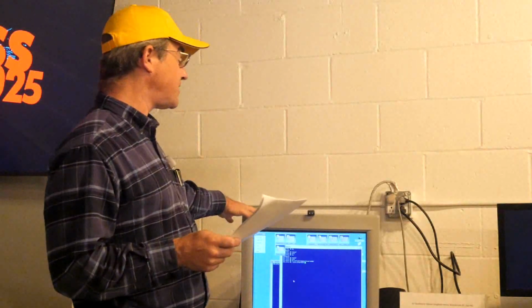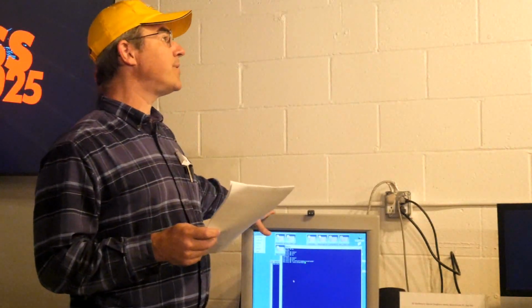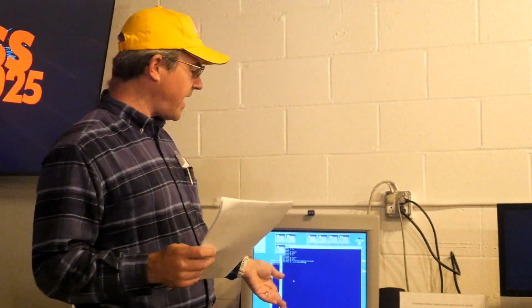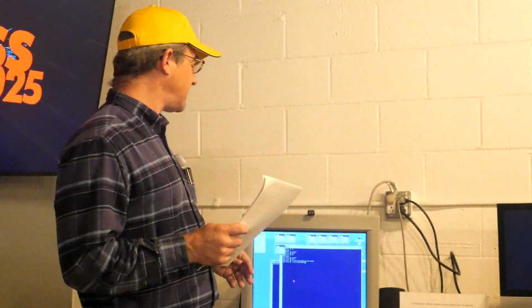And so actually with the Octane, with all the SGI machines, the video output is totally customizable. There's actually a compiler, and you can write a description of exactly what timing and signal levels you want and compile it into this object, which then becomes a mode, and you can set that mode. People create modes to work with 1920 by 1200 LCD monitors, all kinds of stuff. And so I made a video mode that's 100 hertz in stereo.